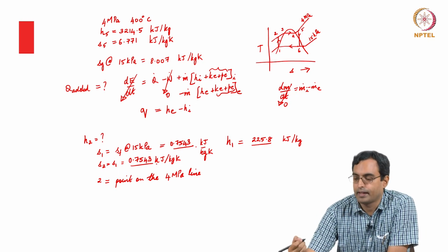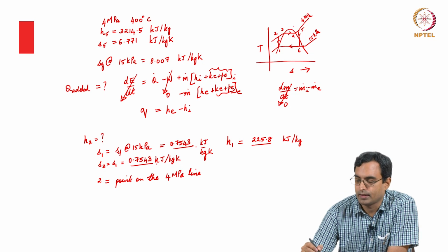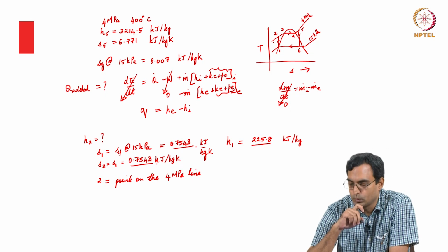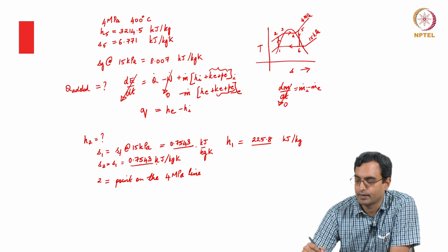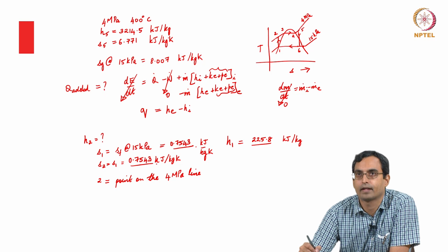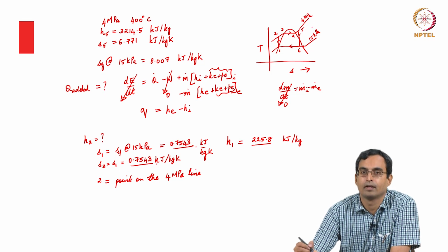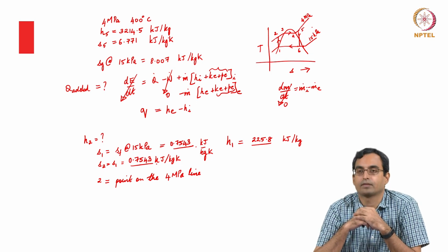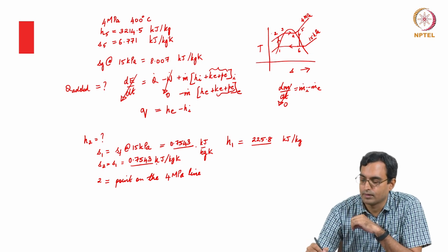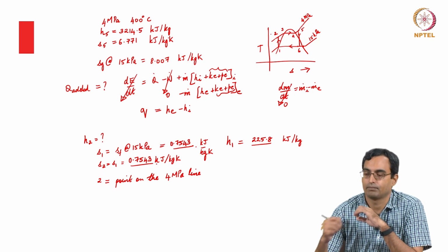In many of the tables, we are also given liquid tables for this region. In the tables which I have been referring to, we have initially saturated liquid and vapor properties, which means we have the properties given on this dome, on the left and right of this dome, and then we have superheated properties which give essentially properties in the superheated region. In the same fashion, we can also look at properties of compressed liquid, which would give you properties of the fluid in this region over here.